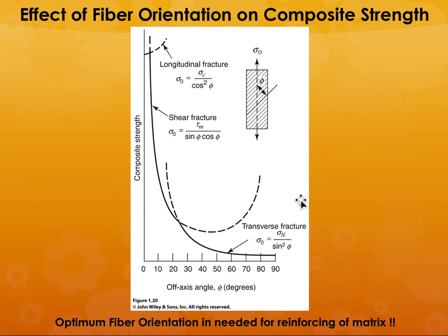So you can also see that there is an effect of fiber orientation on the composite strength. If the angles are different, they can have some benefit, but they don't always benefit completely. Which means that if you have somewhere between 50 and 60% fiber volume in the composite, that is the best, and the matrix is just there to hold the fibers together.